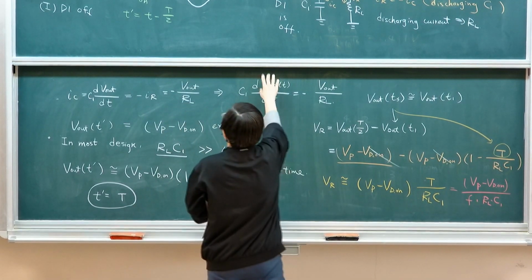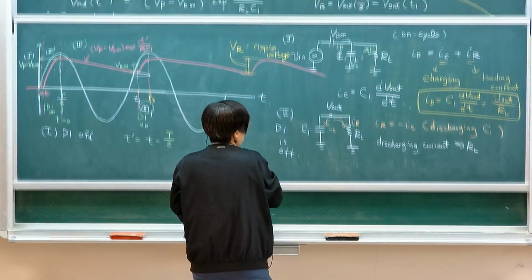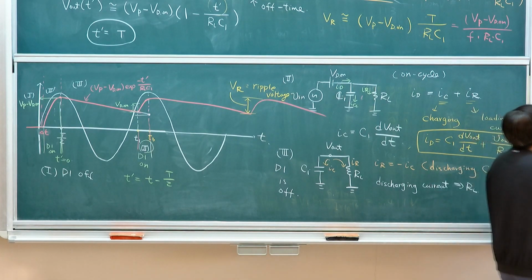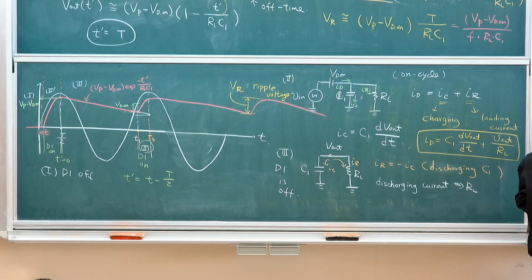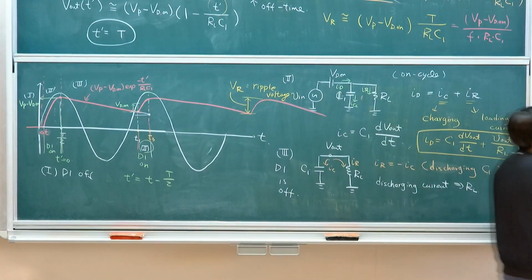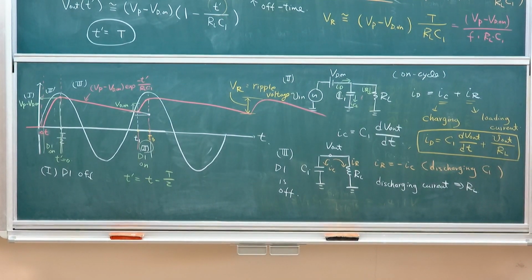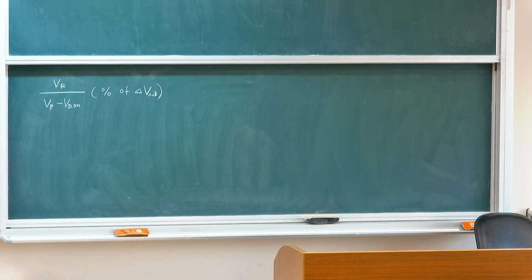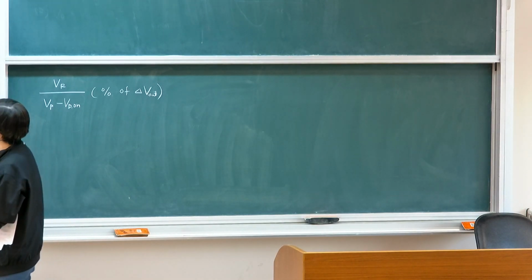So what's more interesting, rather than the absolute ripple voltage, what is typically more important or more meaningful is actually the ratio. So the ripple versus your peak voltage, if I'm rewriting it, this is a percentage of fluctuation in your output. So this is the percentage of delta V at your output. This is the thing that we're delivering out into the adapter. So you're typically more concerned about the percentage of variation. So what determines the percentage of variation based on this equation is